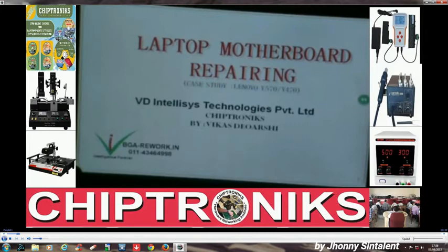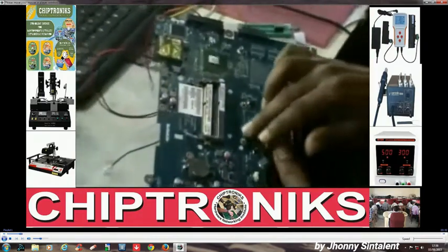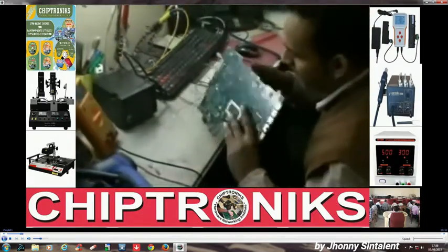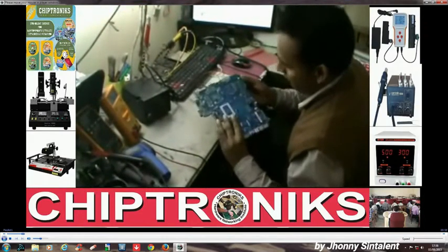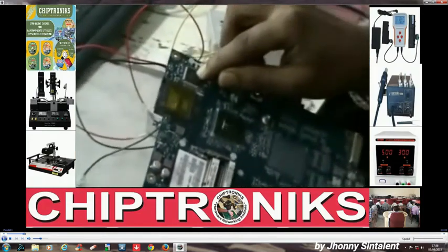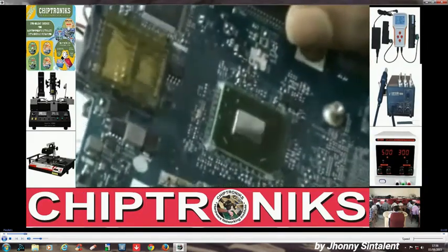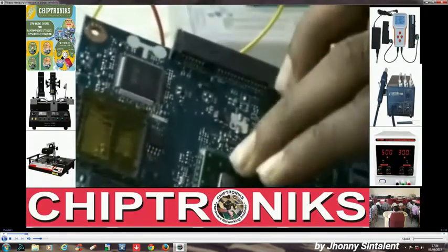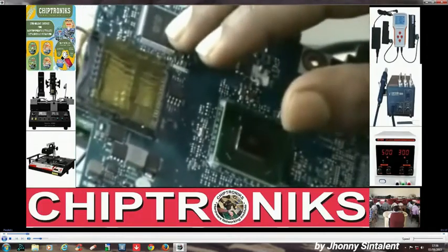This is most commonly found in boards which have an integrated CPU. Like I have the Dell Inspiron 3521 board, where you can see the CPU is integrated, and I have the IO controller KB9012QF, and this IO has embedded flash. On this board you'll find two kinds of BIOS chip. Both are connected with the PCH, and the EC BIOS is inside the IO controller. So that's why